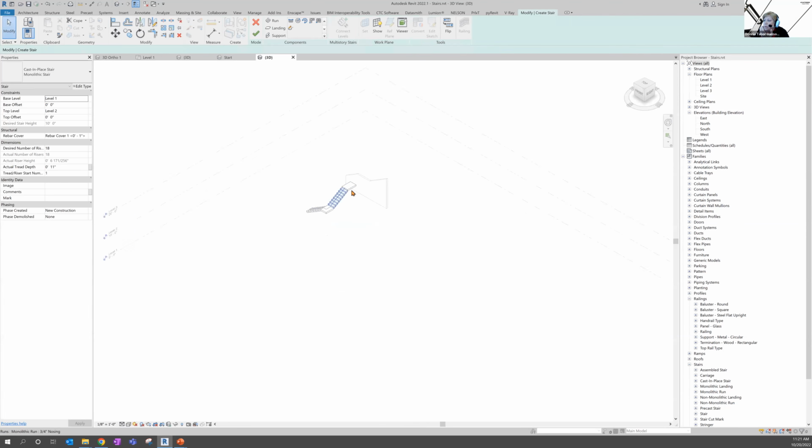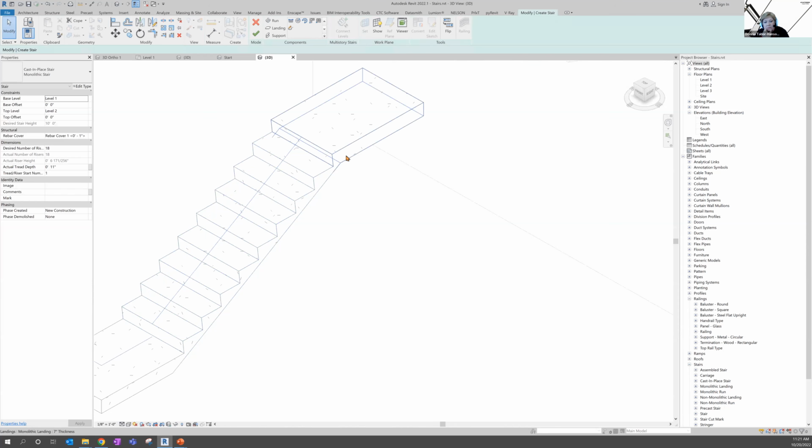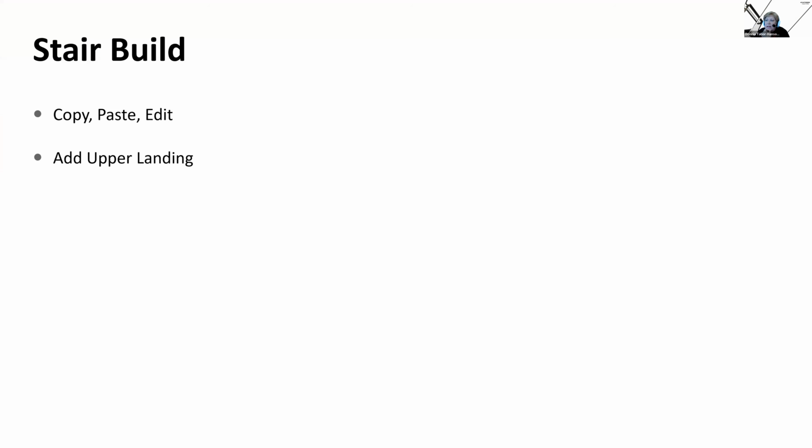But if you've been drawing floors in there, well, I see this also has the continuation of the stairs. So dropping a landing on one, very simple. I mean, this one's built automatically when you do the turn, but to get the landing on the top, very simple. A lot quicker than drawing in a floor or something like that. You can just add the landing if it's going to be part of it. And when you add an upper landing, you can't add one on the other side.